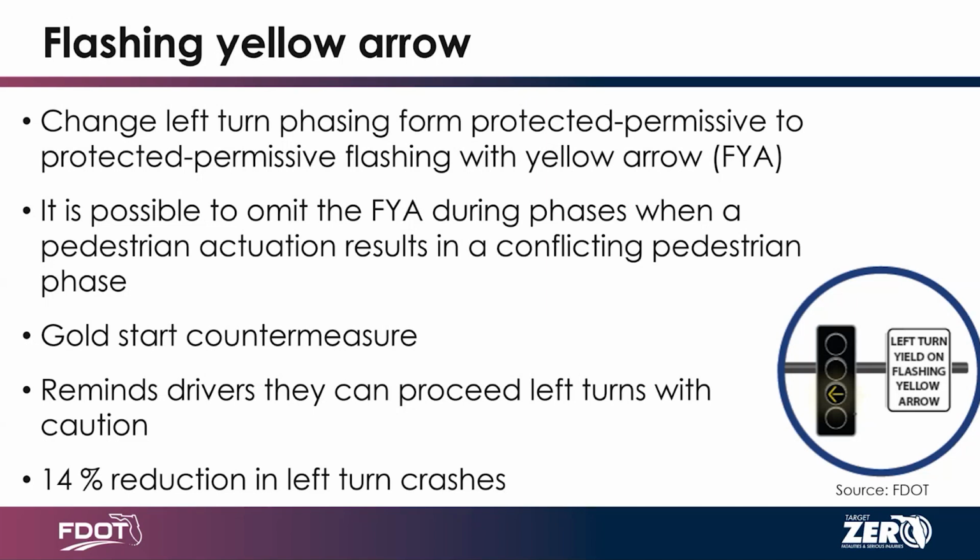I will say one of the dangers for the yellow flashing arrows is because you can change whether it's protected. The benefit is that by itself, it is not the safety measure. The protected phasing portion is the safety measure, right? So it's contingent on it being timed for the right times. The idea being when it's super busy, when you're having the crash issues and the conflicts, you can have it protected. And then at times of day, like say the middle of the night when no one's out there, you can make it permissive so it's not an issue.